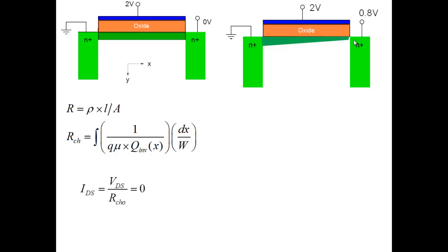I said the width, don't look at it. This width is just a schematic drawing, to illustrate that the amount of inversion charge is less. Width is like a sheet; width has got nothing to do with it. There's no width information in this particular diagram. That's why this diagram can be confusing. Don't talk about width. So the resistance here would be higher.